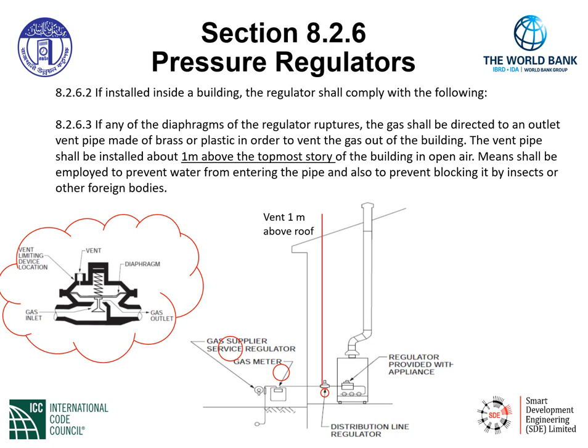There's a section view of a regulator, and as you can see, this is a flexible diaphragm. Sometimes the diaphragm may be damaged. It could rupture, perhaps. When we have the gas coming in on the inlet and going above the seat, the regulator part of the diaphragm increases and decreases, providing a cavity for the volume of gas to flow up over the seat, but it will not allow the gas to flow beyond the diaphragm.